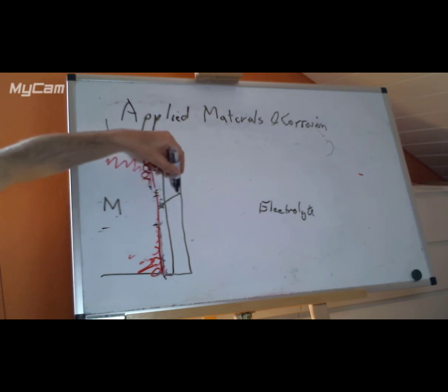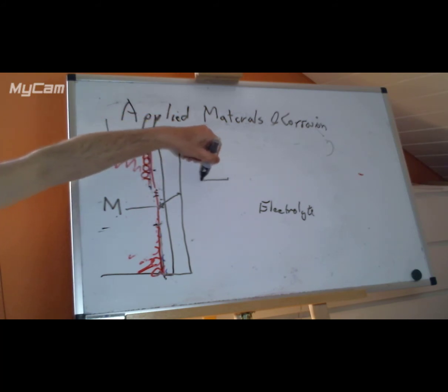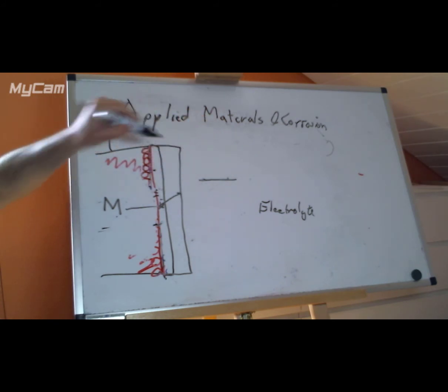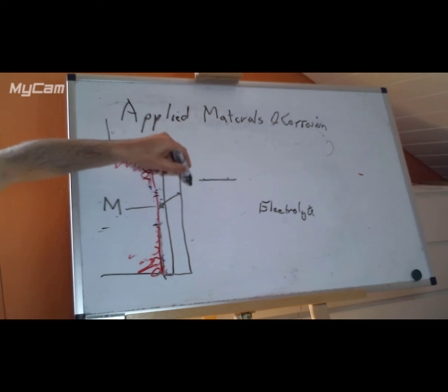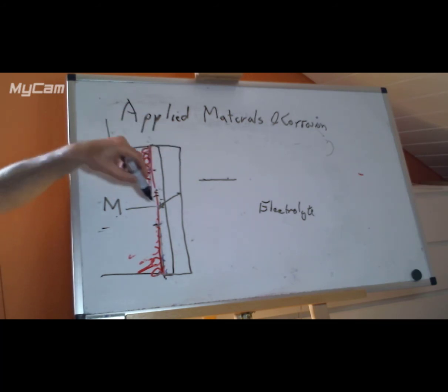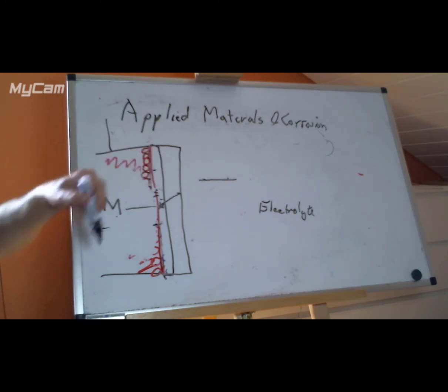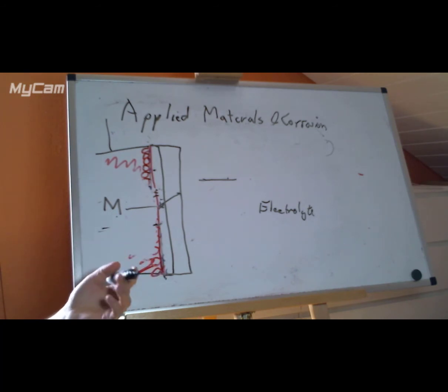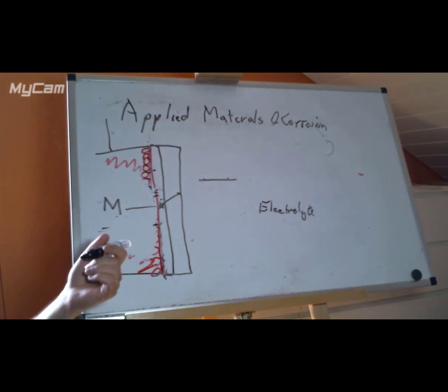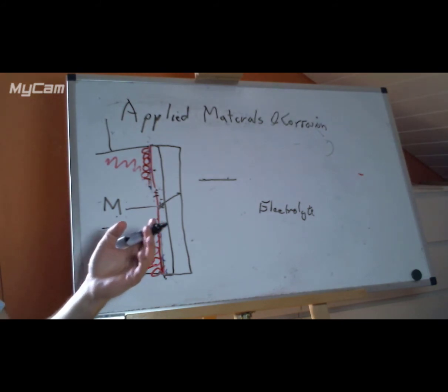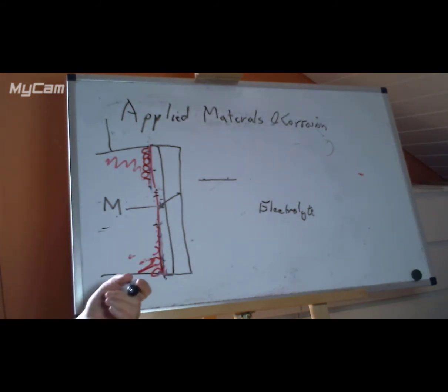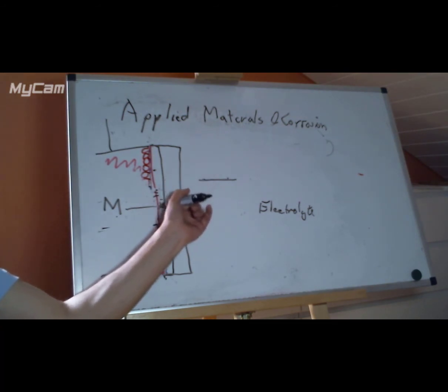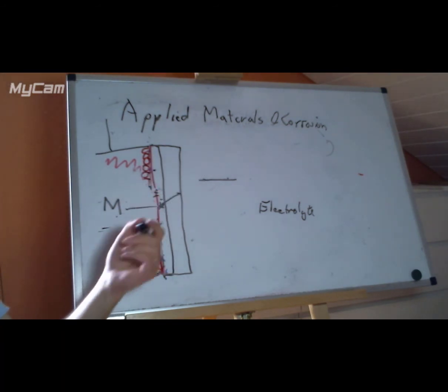So we're going to be effectively lowering the voltage at the interface, and then we're going to drive a reaction between our electrolyte and the oxidation potential of our metal. So the difference between those is going to drive our reaction, which allows it to go. And the steepness of this depends on the resistivity and the thickness and the current. So then we can effectively build up an oxide layer, but it will slow down as it gets thicker and thicker, because the driving force is the difference in energy and difference in electrical potential between these two.